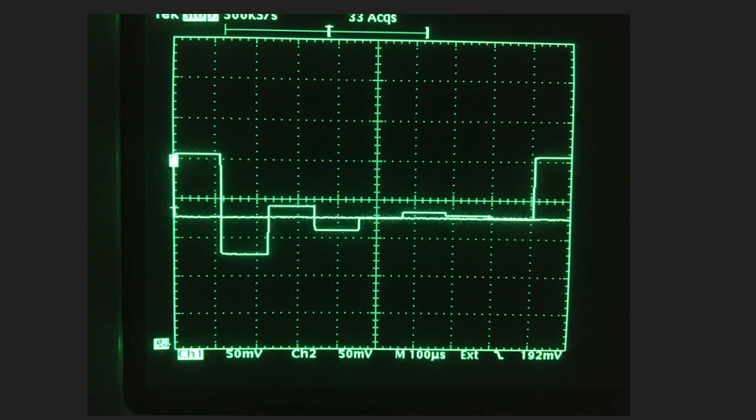Then it's going to drop down to a quarter. So it's going to halve itself and subtract that. So it's going to go down to a quarter. And now it's less than the reference voltage. So it wants to jump back up. The weighting bit's going to be a 1. So our second most significant bit here is going to be a 1. It's going to jump back up and down until it eventually reaches an equilibrium state around that 7th bit.